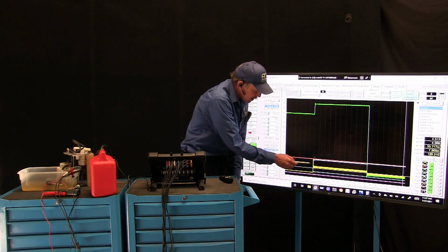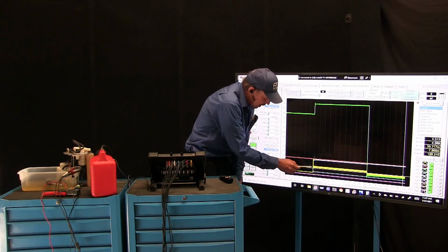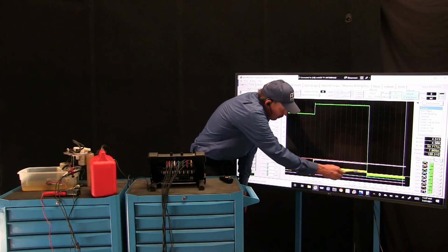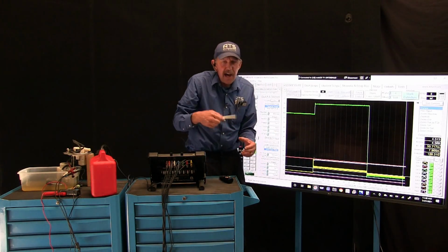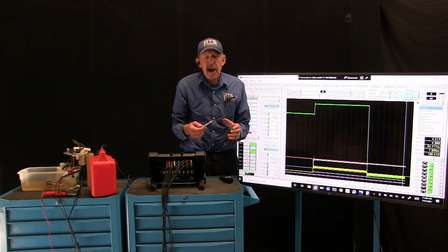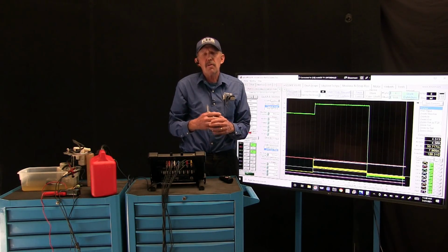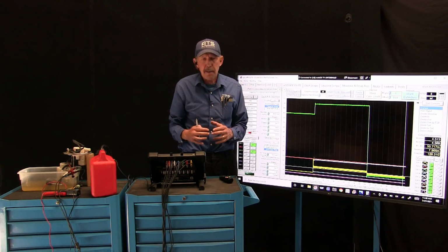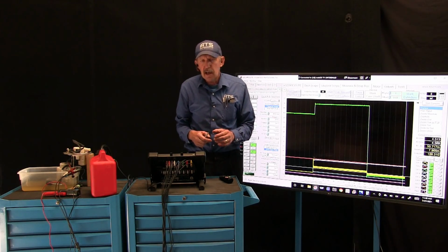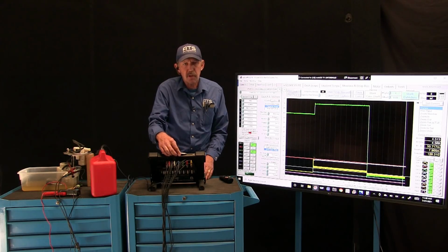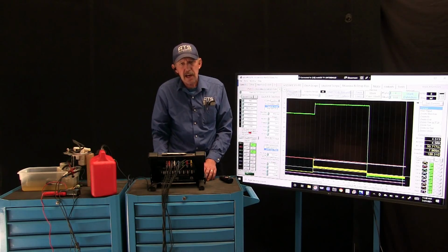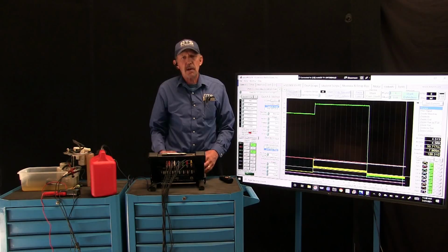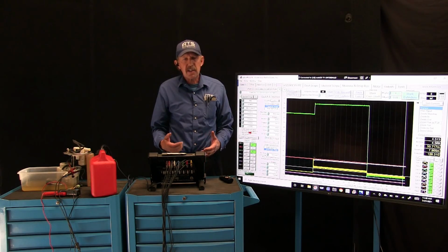If there's resistance in the circuit, I'll see it here. Then we come down and we start to have a current pull. When the pressure drops, we drop current with the pressure because the speed of the pump increased. The faster the pump turns, the more back EMF happens, or the more magnetic fields are building and collapsing across the windings, and that gives me an impedance to the current flow through the circuit. Now, the overall speed of the pump is generally set by the back EMF. It's a product of how this is made.